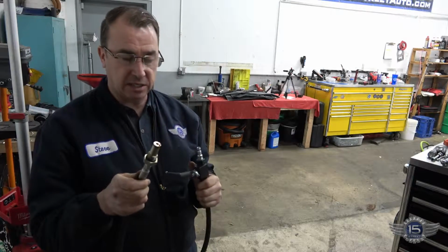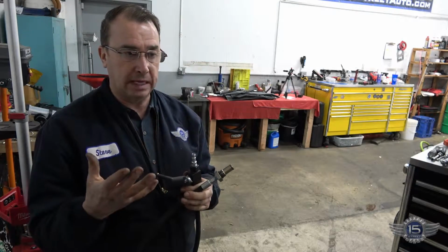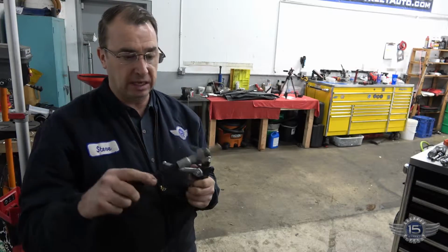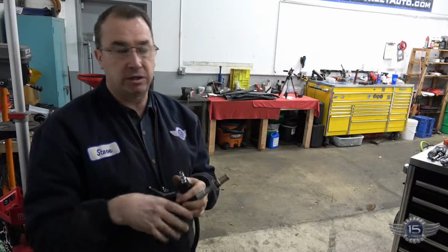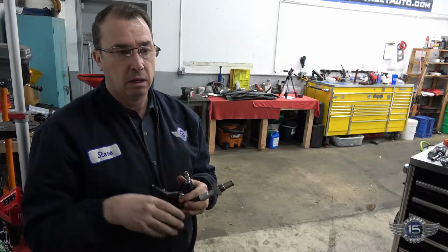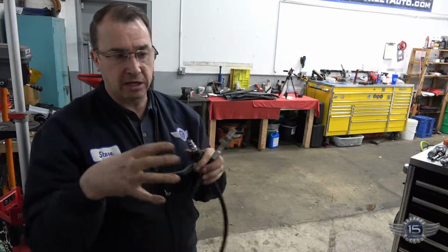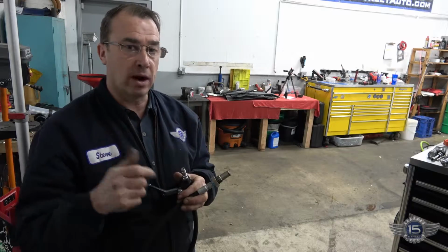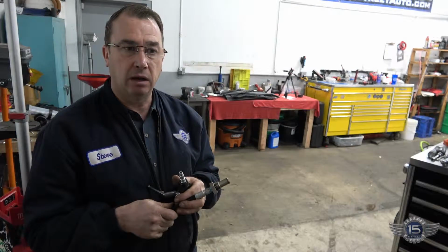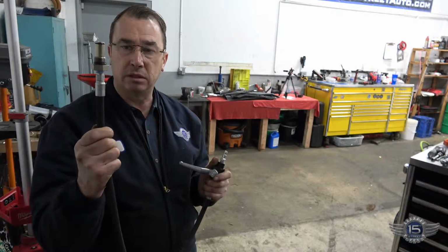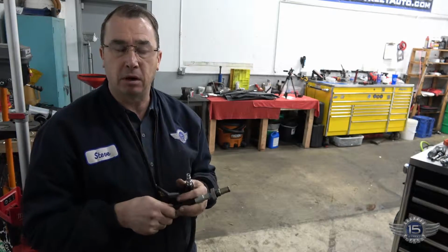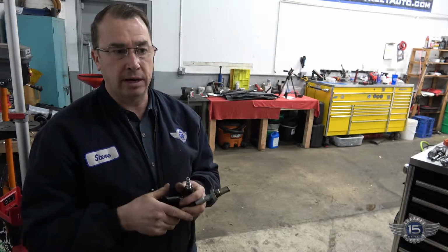And then a second test, after you've determined that there's no leaks, you can also leave this hooked up with this closed, and put the FICM back together, because the FICM has to come off to do this. Put the FICM back in, attach some other lines, and go crank it. If you then have high pressure oil pressure, you know your problem is the IPR, because all you're doing is substituting this for the IPR. So that's what we're going to do right now.